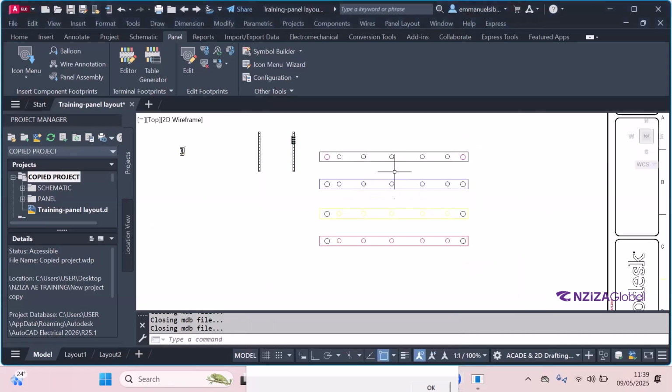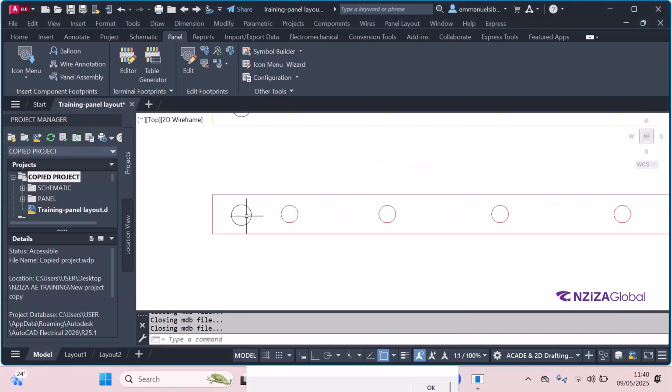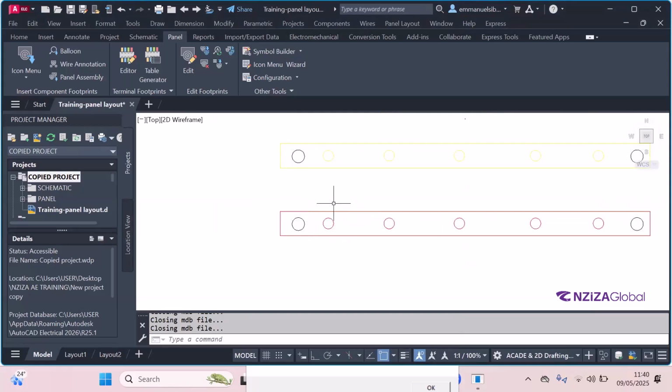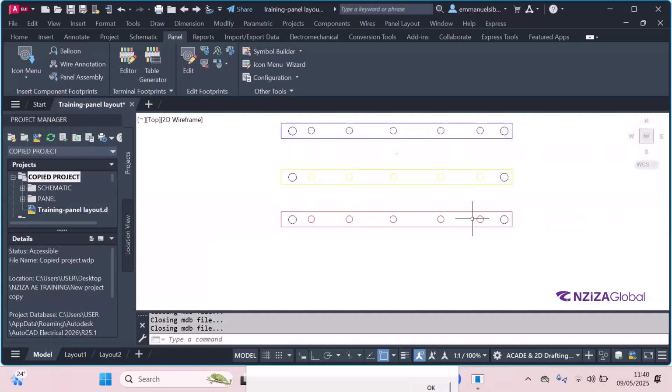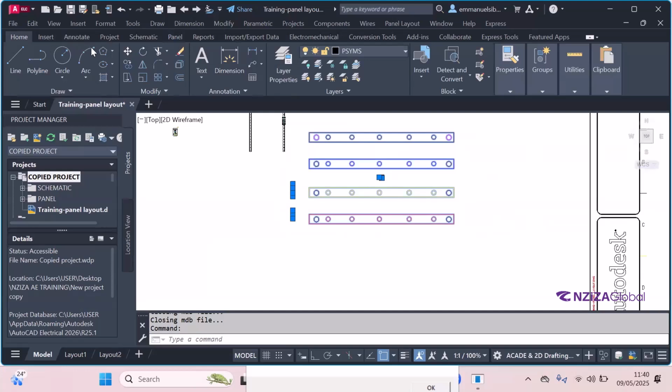For those online, you see that this is the first hole. This last one is the hole you can use to fix this bus bar on a panel board. And those in the middle are where you can connect it to one cable. I didn't show all accessories maybe, because this is the physical representation of this bus bar. Okay? Hope this is understood well.